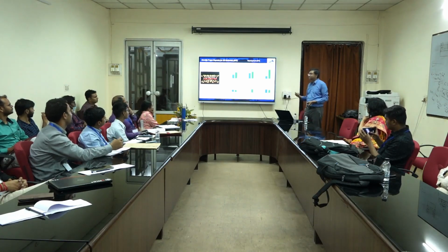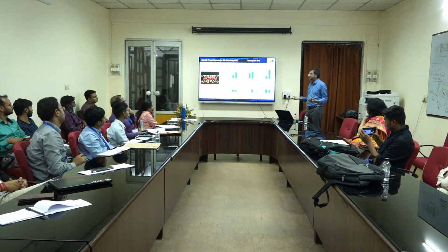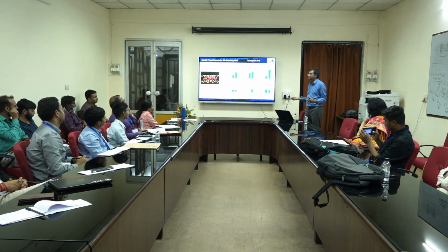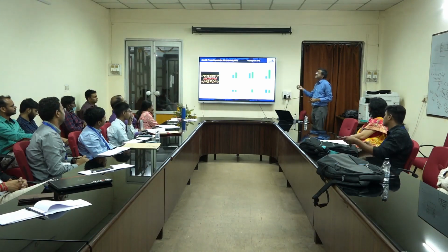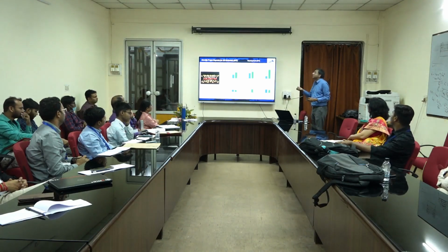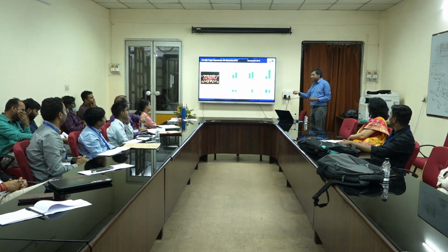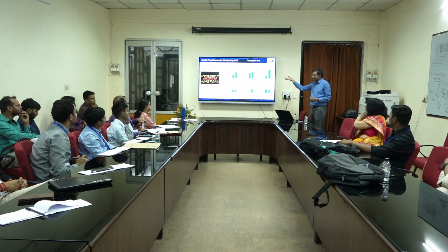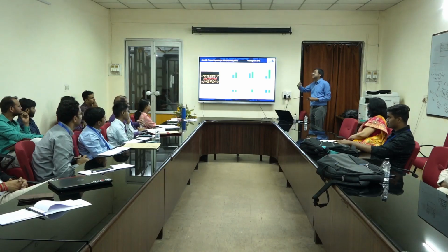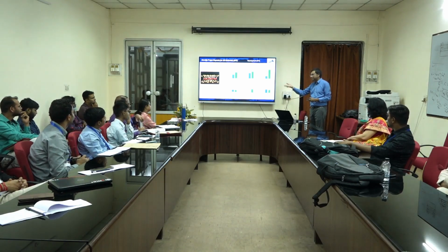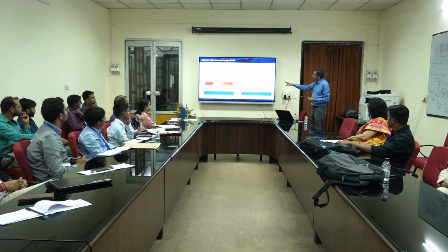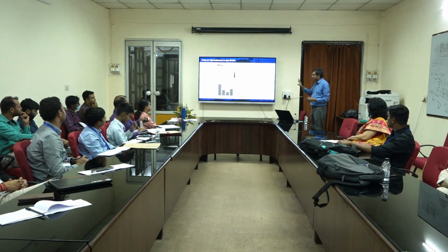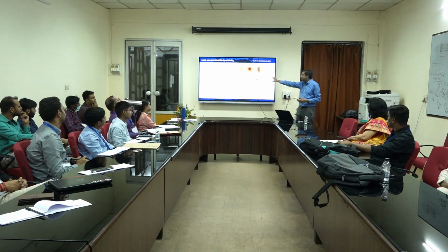And when the doping concentration is so low, even in cross-sectional TEM, we will not find it. You are literally trying to find a hair in a big room in the dark. So it's very difficult to find out the exact concentration. Therefore, we only know qualitatively that once you put a lot of niobium, vanadium, and tantalum, I get degenerate doping in thicker layers. The point I was trying to make is that we understand niobium, vanadium, tantalum are good dopants, and this is the way to go.